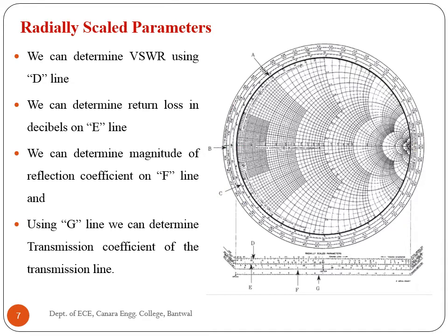Radially scaled parameters. We can determine VSWR using D line. We can determine return loss in decibels on E line.